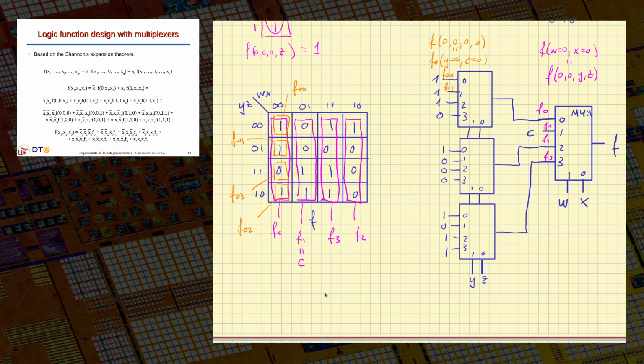Lookup tables depend on the FPGA, but they may have 16 entries or 4 selection inputs, or a bit more or a bit less. Okay, but it's not a problem, because even if your function is more complex, you can combine different lookup tables to implement more complex functions in the same way that you can combine different multiplexers to implement any function, no matter how complex it is.